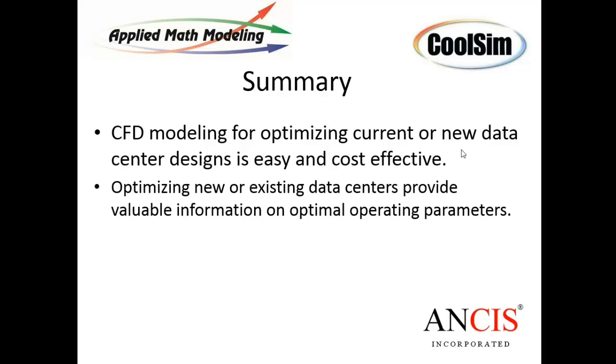The other thing that I just wanted to point out there, Magnus, is that you can always get into more detail, more complexity. You can put in CoolSim the wattage specifically in the vertical position. You can build the entire rack and look at leakage inside it, but we have to make some assumptions about what's going to be deployed here. And this at least gives you a range of where the parameters ought to be.